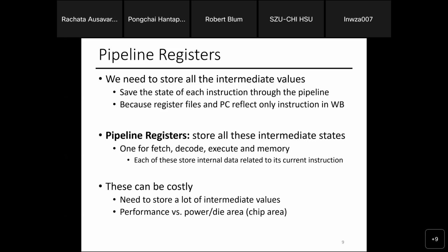The only instance where you still see a simple pipeline that looks like this, which is sometimes 5 stages like fetch, decode, execute, memory, write back, or 7 to 9 stages, is in the microcontrollers that go into devices that you see, like smart things. Those are really tiny chips, and you don't need that much performance. They just need to make sure it runs.